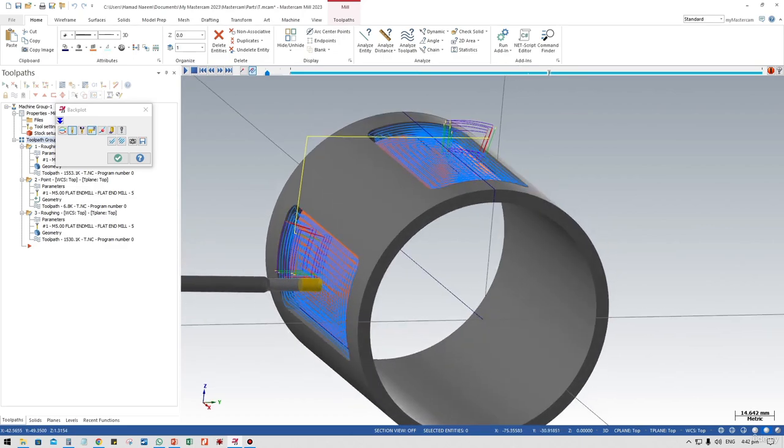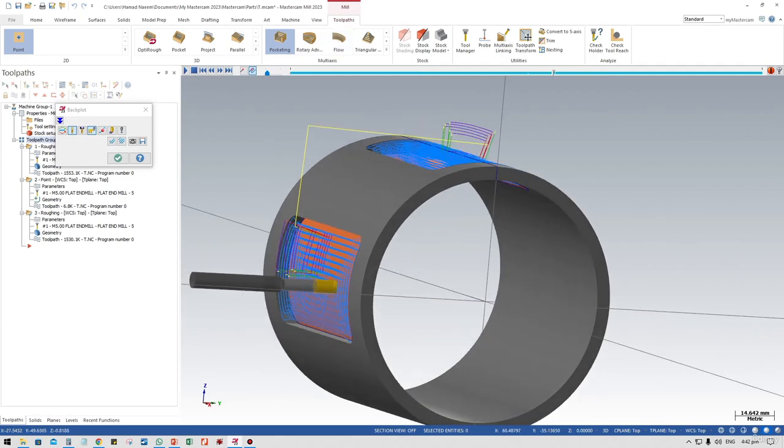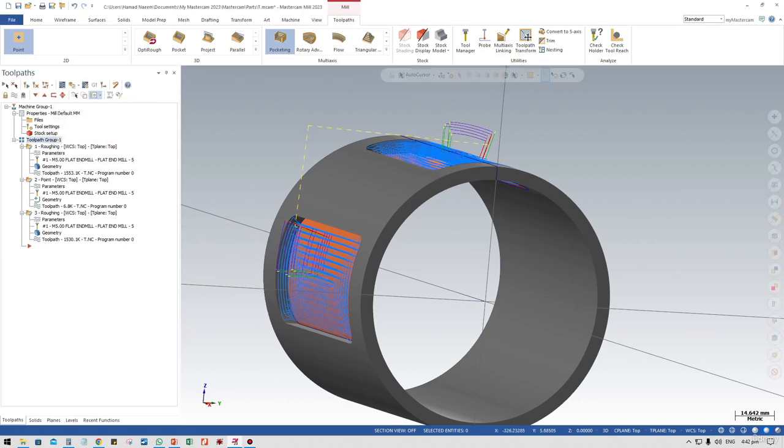After doing the toolpath, we transform the toolpath using the transform toolpath method, and we got an error. So for removing that error, we create a point of reference where the tool will go back and then move to the other toolpath location. Okay. So this is how we can create